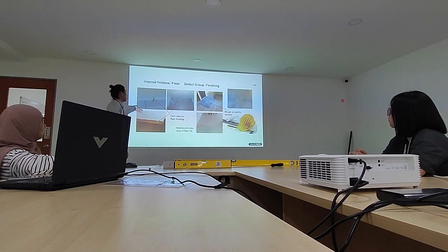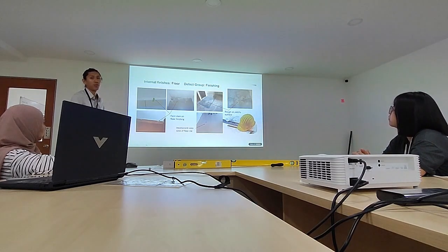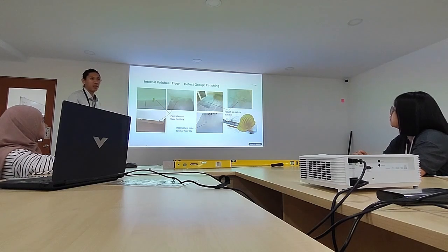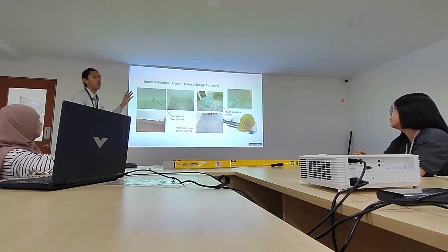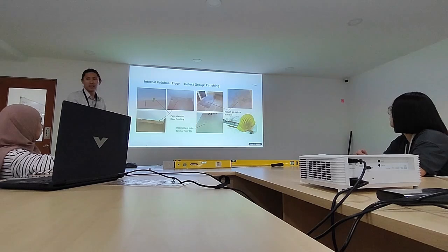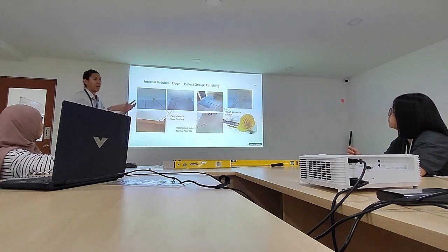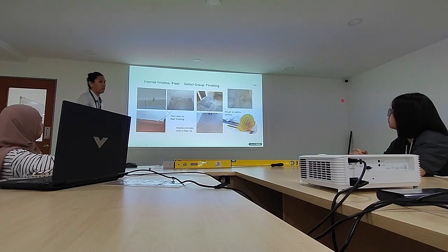So the most common thing that we will see, or we will highlight or point out during the QRC assessment. Why? Because the people who check, it is the last test. After all the objects are finished, the inspectors come in. So when the partition is not covered well, then we will have these things. First thing is the paint is too watery, they mix too much water. Why mix much water? Actually it is a work problem. With more water, they can paint faster, and it is easier to standby the problem. And this is the first thing.